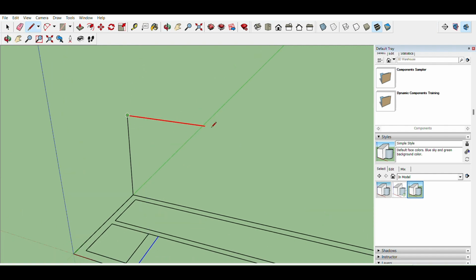That's going to be to the top of the studs, and then counting up from the studs, I've got the floor joists, and I'm going to use a 14-inch TJI joist. Most of the time you'd probably see 11 and 7/8, but if steel wants to be used at any point in this, I'll show you later why I prefer 14.